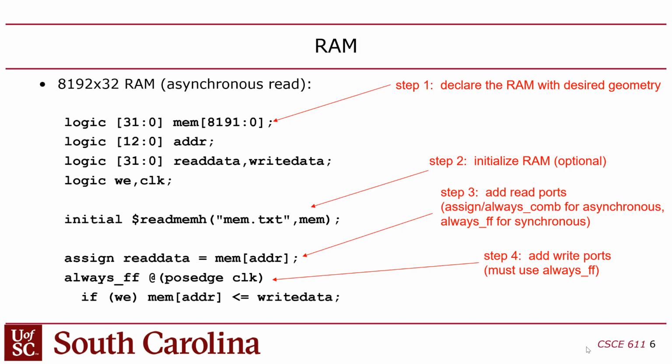I mean, it doesn't have to be an instruction RAM. We used to initialize the register file too back in the day. In an older version of this course, we only had the R-type instructions in the first lab. We didn't have I-type, so there's no way to initialize a register at all. And so we had to initialize the register file to put any kind of initial values in there at all,